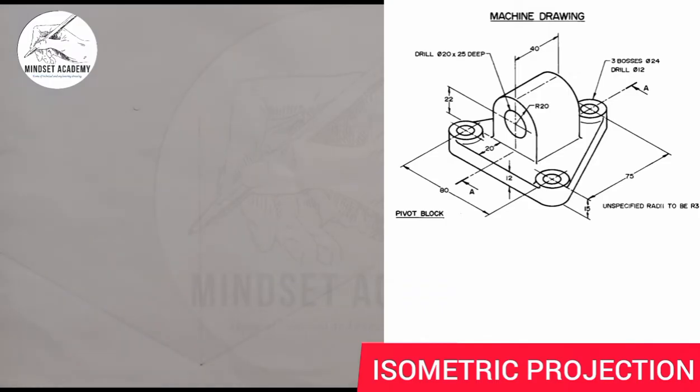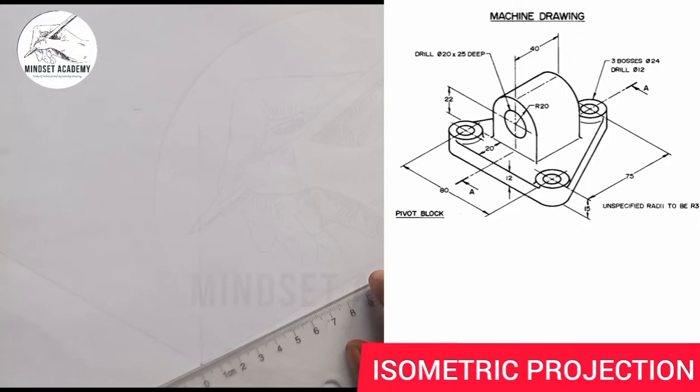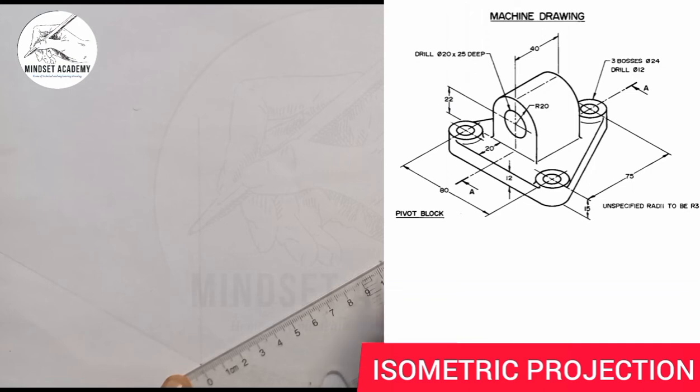Now the entire length here, at this point, is given to be 99. How did I get 99? The radius of this circle here is 12, because the diameter is given to be 24, and we have two of them here. So 12 plus 12 is 24. The 24 plus 75 is 99. So I am going to measure 99 from this part here, from 0 to 99. From 0 to 99,